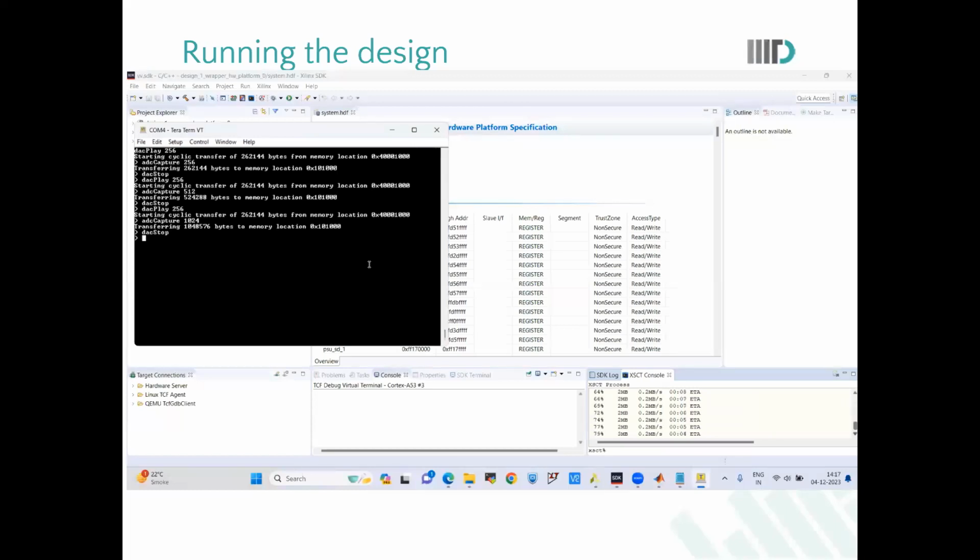Once you give the source download waveform.tcl command, then you can directly capture by giving the ADC capture command from the Teraterm window continuously, to capture more files from here. For 1024K you need to give ADC capture 2048.